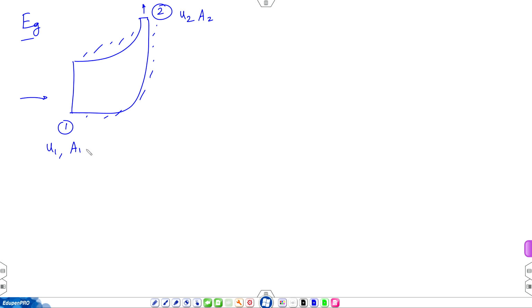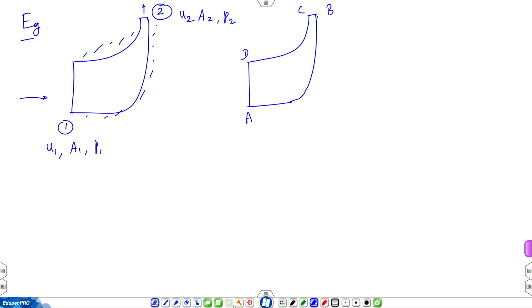So, it is an internal flow problem. This is P 1. So, you will not refer to any far field condition. Pick a control volume, A, B, C, D. Of course, A, B and C, D are part of the same surface, and u dot n is 0. So, applying mass balance, you will get minus u 1 A 1 plus u 2 A 2 equal to 0.